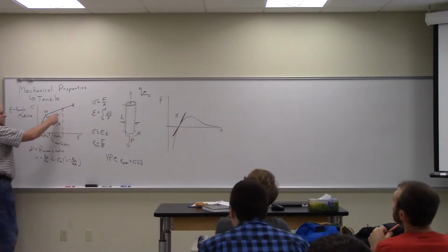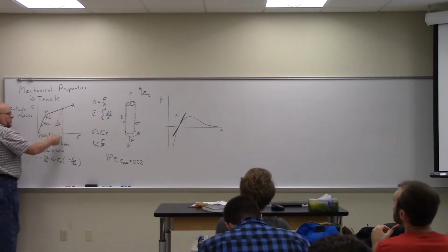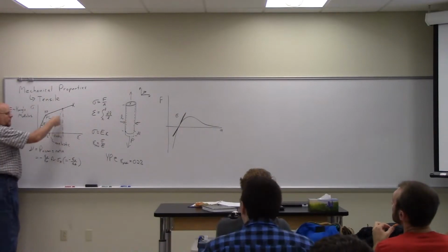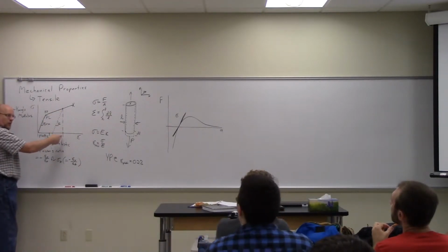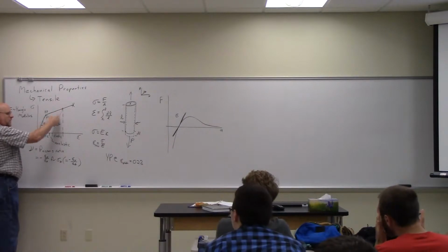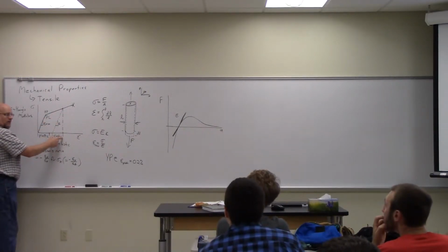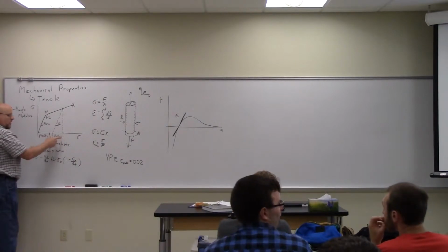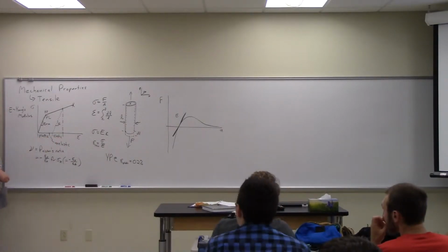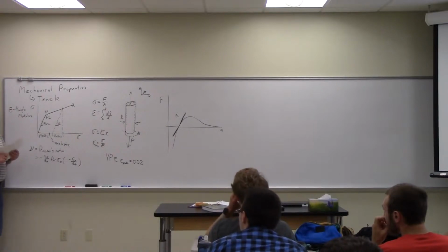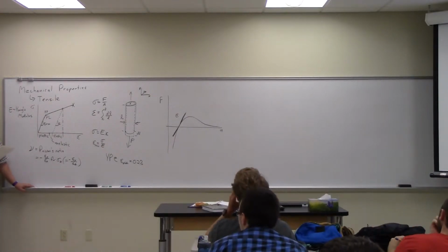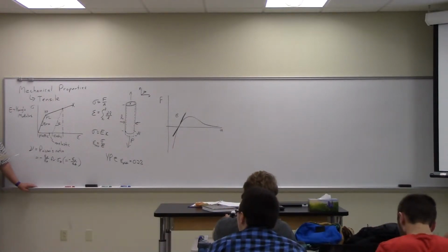No, I mean, think about it. I stretch it, it's this long now. Right, it's undergone 50%, it's 50% longer. I let go of it, it comes back, now it's 30% longer. Which means there was 20% elastic that was recovered, and 30% plastic that's left. So plastic is basically whatever it is once you let it go. Right, plastic is what's there when you let it go.